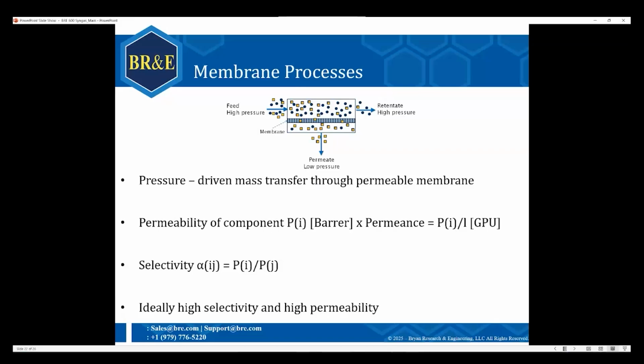And for our syngas process, both hydrogen and CO2 selective membranes are relevant to use. Which membrane to use depends on the pressure and purity requirements of your product. Permeate will have lower pressures since it needs to go through the membrane, and the retentate usually has higher pressures, but not that high purities, if we have also other components there, and two components that we want to separate.